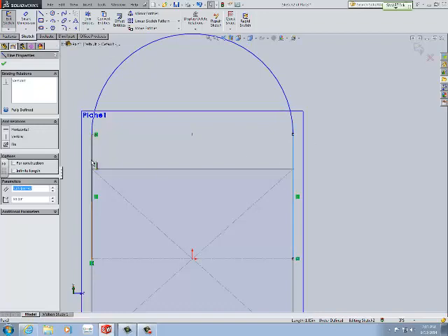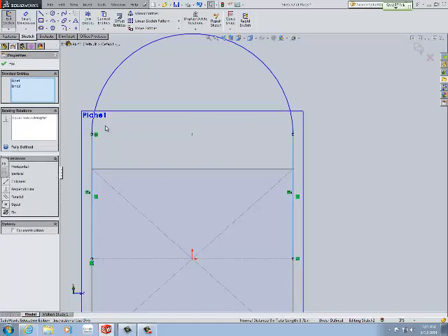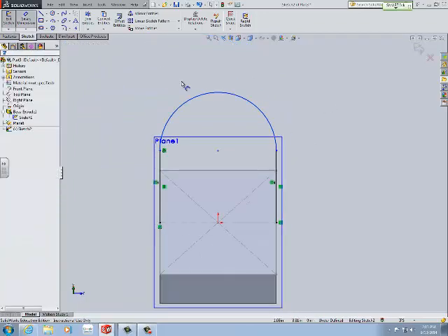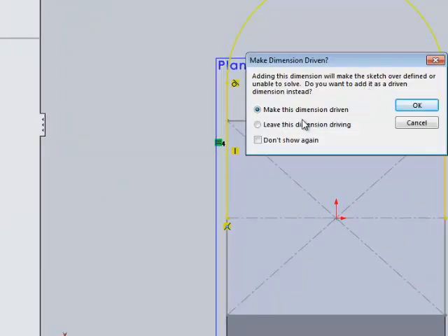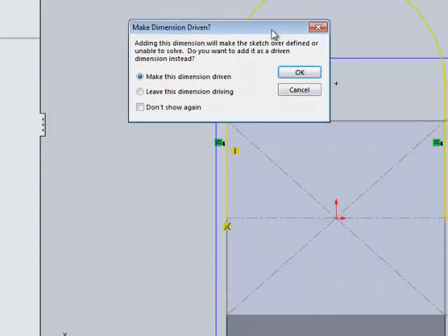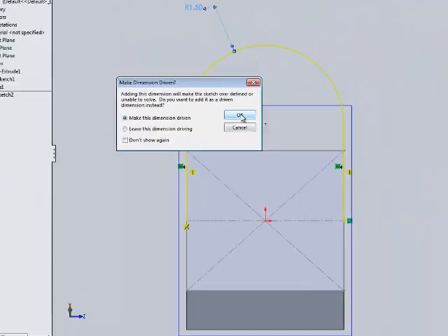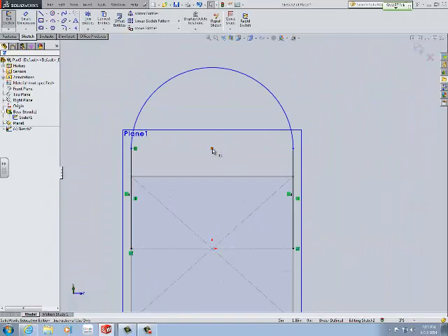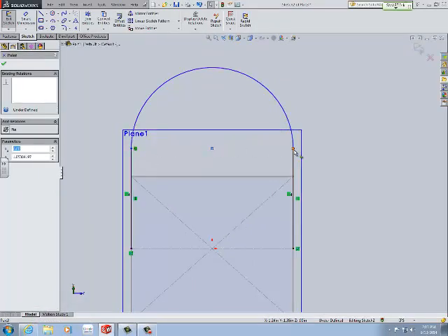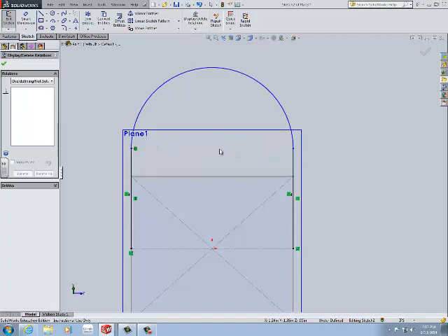We make these equal. Which actually is our second step. We should do the radius first, which we already know, which is actually just the size of the part. We don't want to give it a size dimension style, because if we decide to make the part wider, but we want to keep the same diameter for it overall,